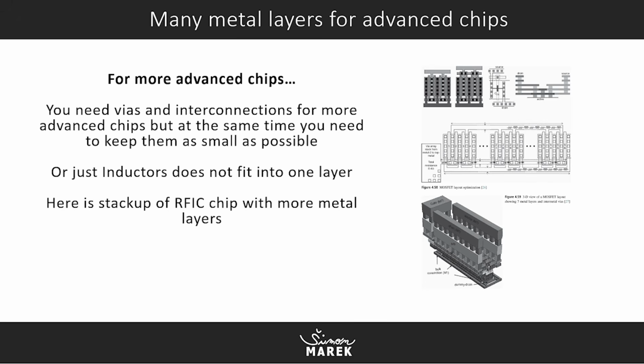Or your inductors just do not fit into one layer, or you need to connect your inductors or your transformers or balun transformers. So you need multiple metal layers. So there's our metal stack up for RFIC circuits.